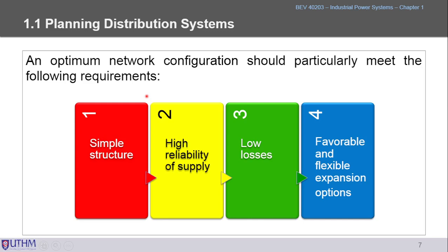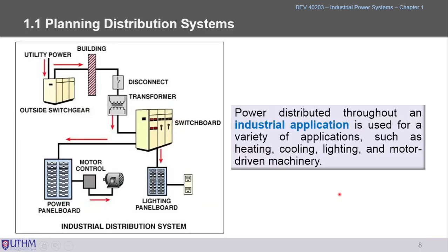But for the IPS, the percentage is between 15 to 30%. That is following the standards of the electrical installations. For the IPS, we need to have some expansion options, or we call it a spare, of 15 to 30%, right?